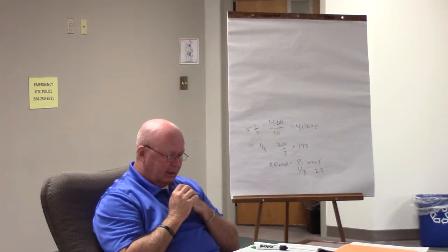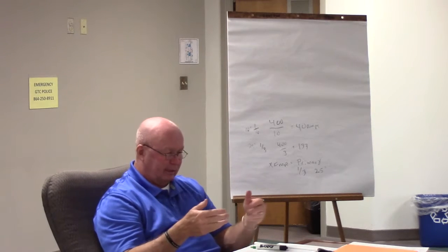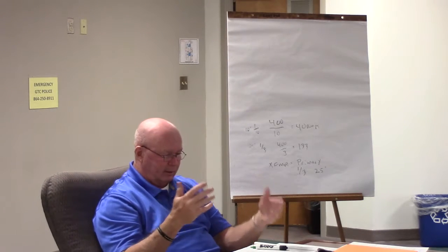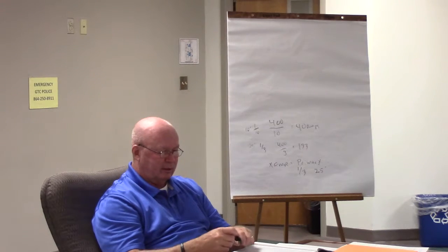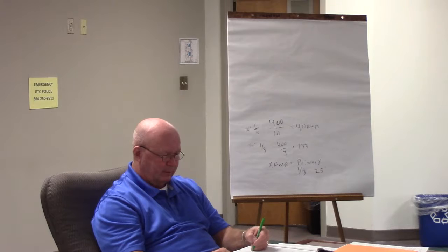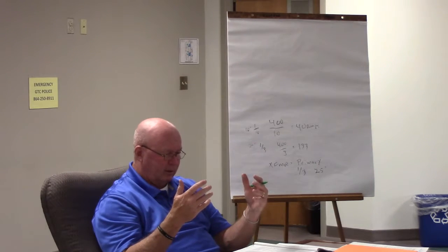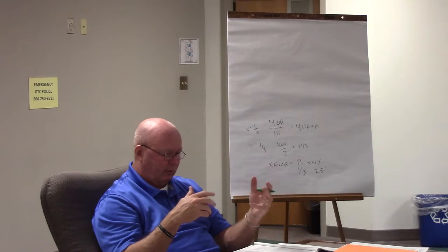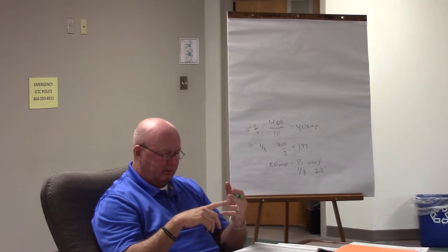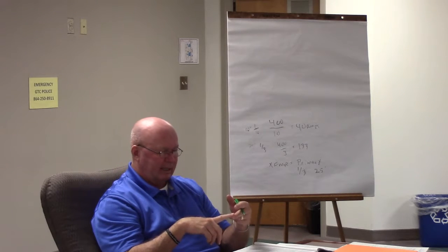Okay. Number 4, I think, is kind of self-explanatory. It's the same rule in everything that we do. You have to put it in what? For us, we're putting it in what? Raceway. Yeah, we're putting it in a raceway. Okay. And the last bullet point is no different than what we were saying before. The secondary conductors must terminate in a single circuit breaker or set of fuses that limit the load to not more than the conductor ampacity permitted in 310.15.